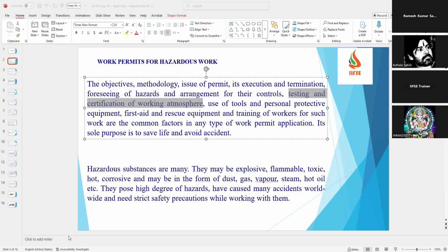Real monitoring. Yes, perfect example. So basically, I can give an overall example as confined space, even LEL. LEL, we need not do only in the confined space. Whenever you are doing any process areas, hot work, there we do this LEL monitoring, lower explosive limit.